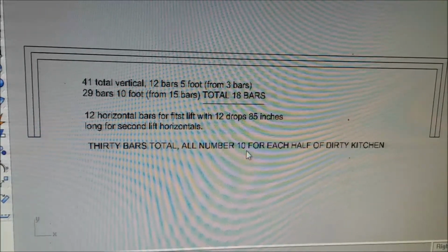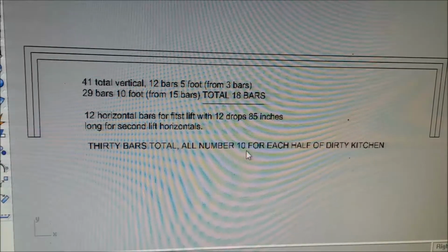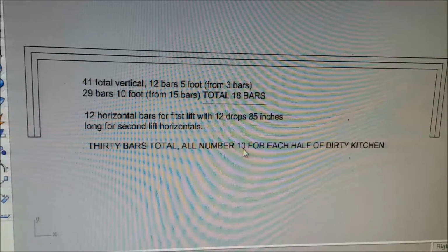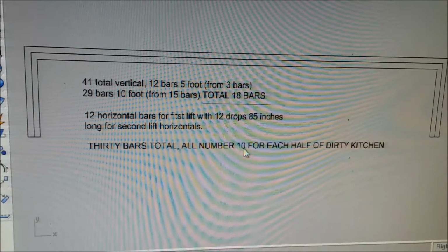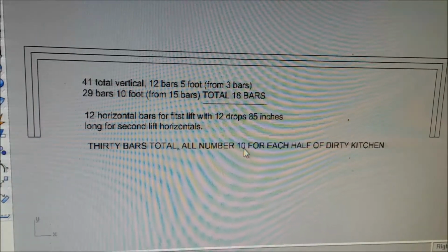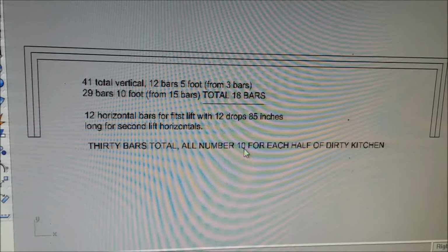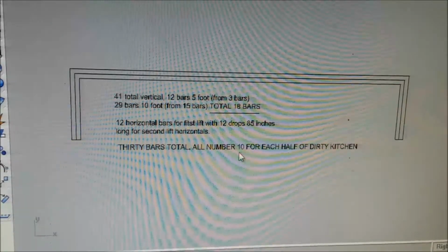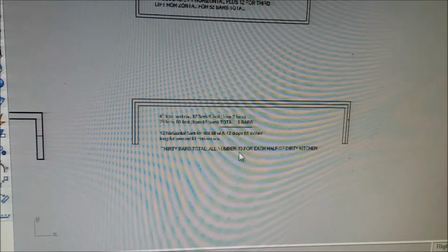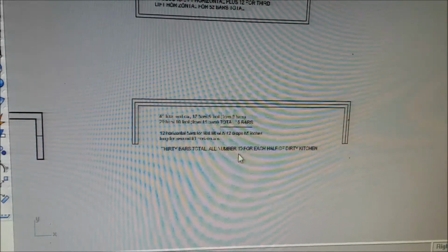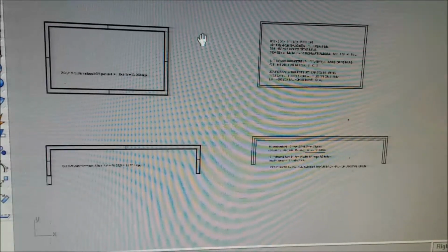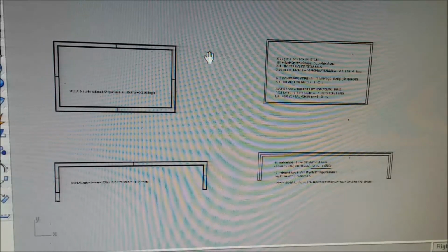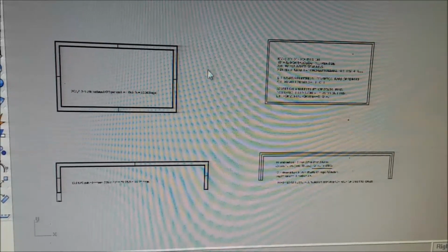Apparently, with the 9-inch spacing between bars, we can use number 10. If we go maybe 12 or 12 and a half inches spacing, then number 12 bars. But if you're trying to restrain cracks, more bars is better. You have a better chance of having steel at the crack. So that concludes what we're doing here.